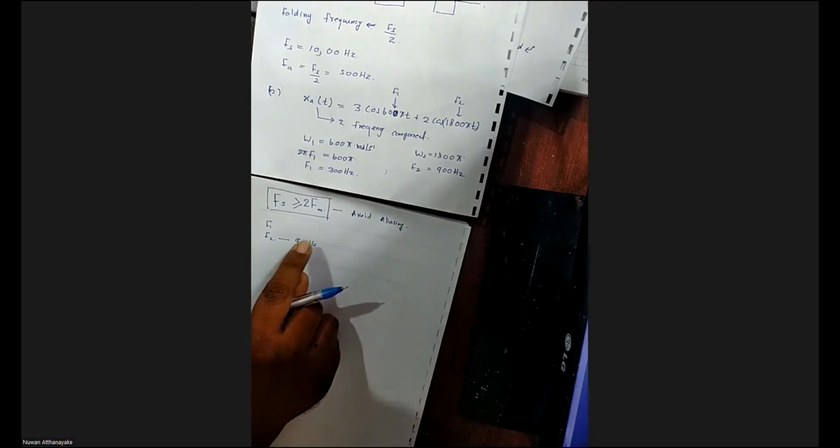Thank you, Ahmad. So if you select your sampling frequency greater than twice this highest frequency, it will not create any problem.